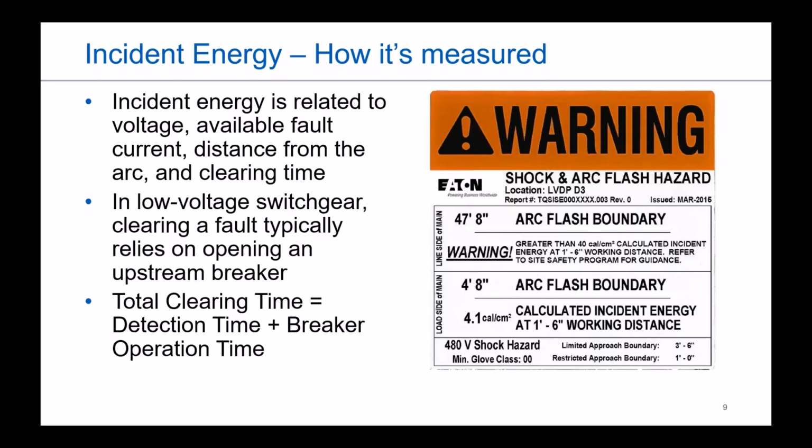So when we talk about low voltage switchgear, we're really talking about what's that main low voltage power circuit breaker that's upstream that is going to be able to open for us. And so the clearing time itself, when we're talking about breakers, it's not only how quickly can the system detect when there is an arc flash or when we have a rise in that current level, but then also for that circuit breaker to go and perform its operation so it can de-energize the circuit.